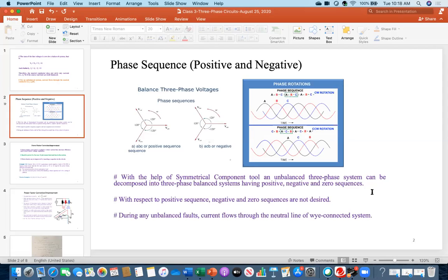So that 30 ampere will be divided, maybe equal or unequal values, but those will be trapped in the 3 coils of the delta connected system. Consequently, those coils will also be overheated and at some point maybe burned. That's why zero sequence is very detrimental, very harmful for the system.